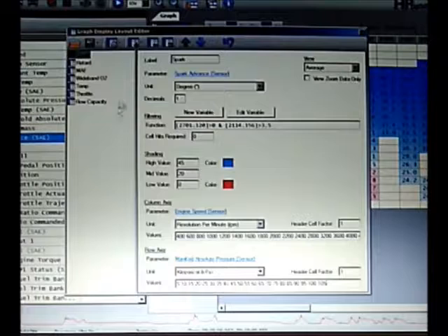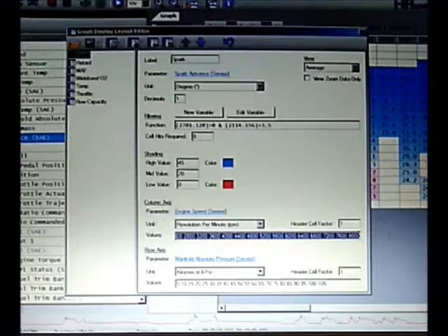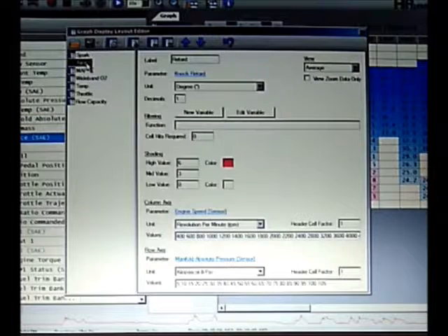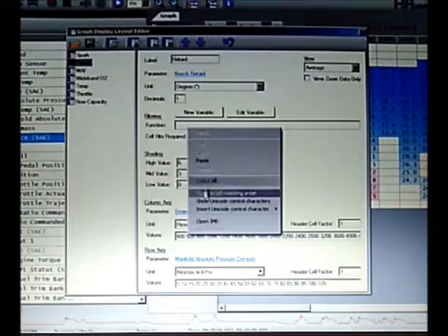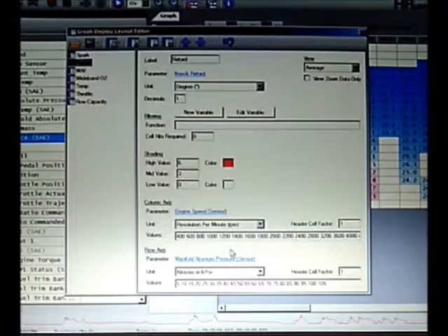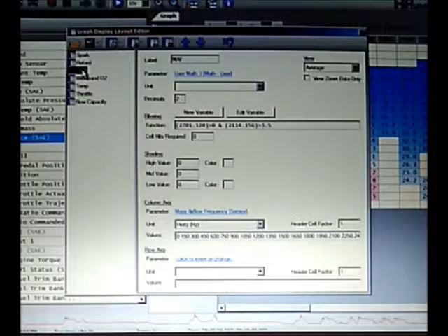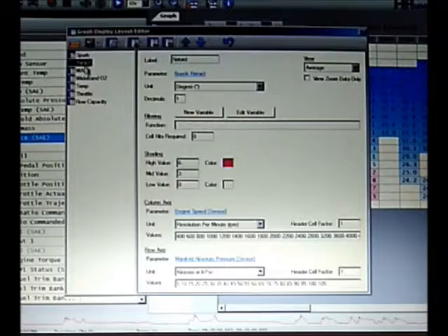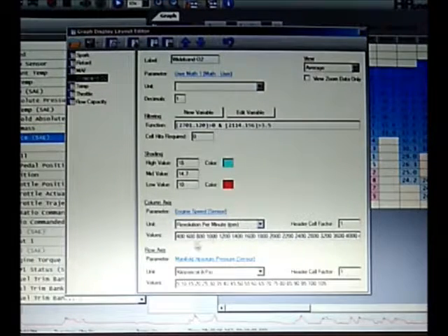And then once you've got one of these charts good, what you can do is just highlight, select the entire row, right click, copy it, and then for the next chart, like the KR, the knock retard, you can just put your cursor here, right click, and paste everything. So that way you don't have to type it over and over again. But basically, like I said, the Spark, the retard, the MAF, the MAF doesn't have the same format. The MAF is a one-dimensional table, so forget that I said that. The Spark, the retard, and the Wideband O2, they all have the same column and row axes.